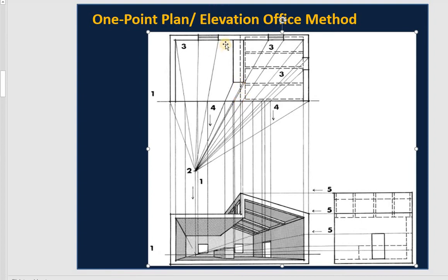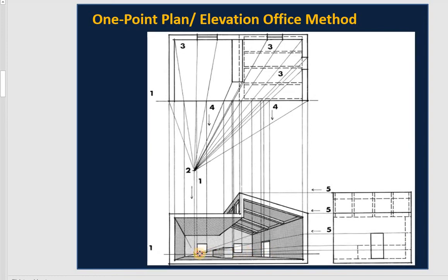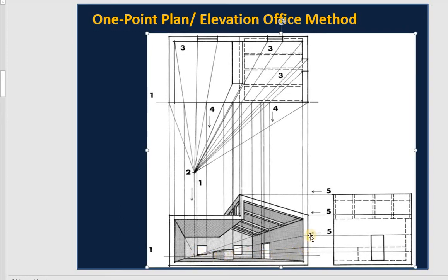So this is the window. You draw from standard point, draw the lines to the point from the window, and when they cut in the picture plane, you drop down there, so you can see this is the window. Do the same thing with the other line. You have the lights right here for the window, and the window right here, you look at this, it's the window side, so you can move this one for the true height from the window. After that, connect with this point right there for the view.